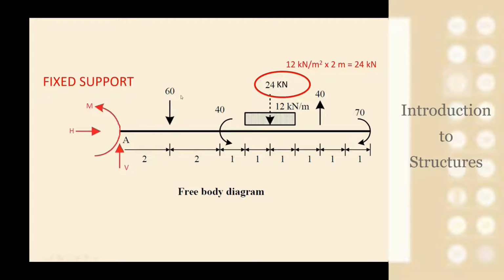Again, you see here that I have deleted the signs of the forces, because in engineering, in order to avoid confusion, we sometimes prefer not to put the sign of the force, but show the force with its direction. For example, here it's clear that this force is coming down, so it's negative. And we are going to take the signs into consideration only when we write equations.